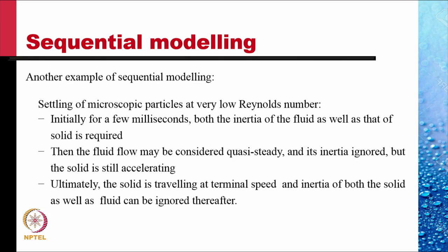Another example of sequential modeling is the settling of microscopic particles in very low Reynolds number flow. This also we had done earlier. Initially, for a few milliseconds, both the inertia of the fluid as well as that of the solid are required. The fluid is accelerating, the solid is accelerating.